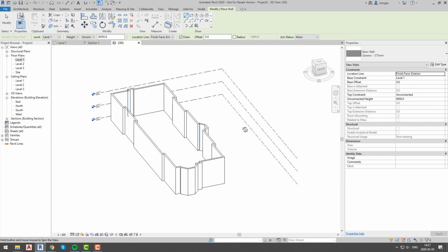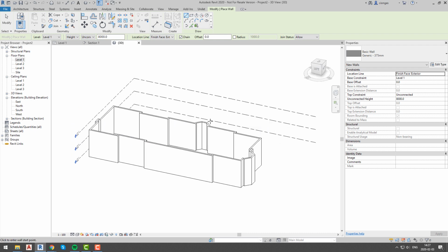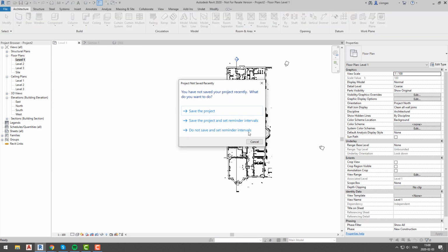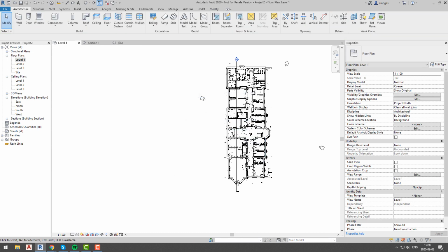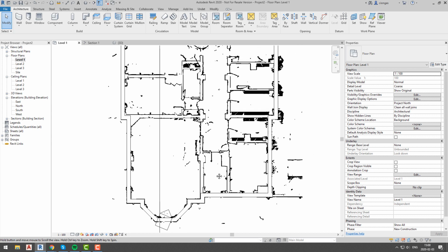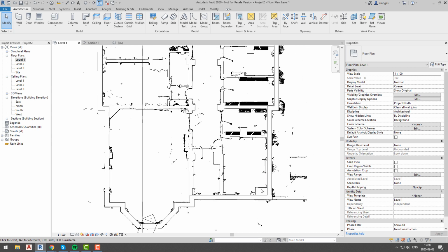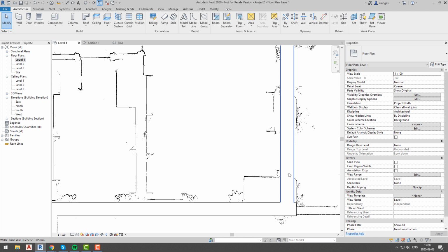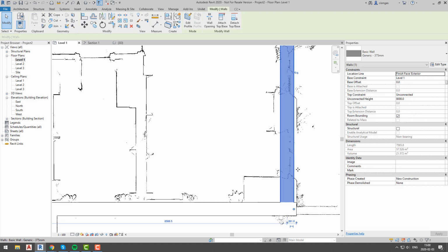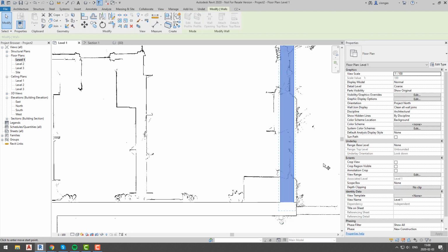Let's jump into 3D view to take a look at what we modeled. But while modeling we noticed that some walls have different thickness than others, so we will go back and we will adjust walls positions and thickness so that they will be precise according to point cloud information. Before doing that we will open visibility options and add transparency to our walls. It will allow us to make adjustments faster.